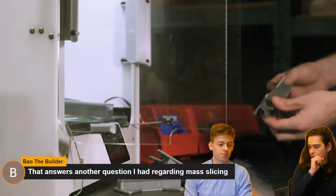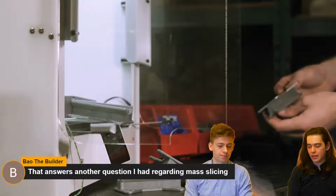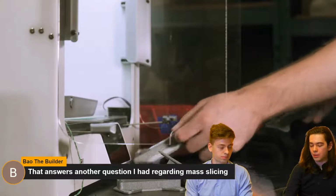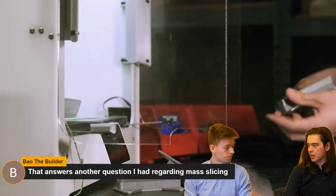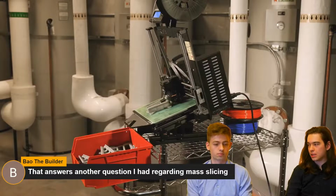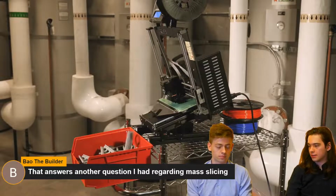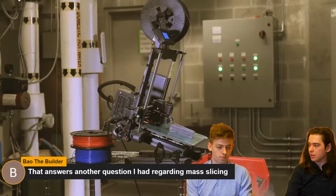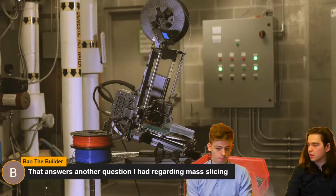Exactly. Because you would know in Pro, you would be sending it as a silk PLA job. You could have an offset for silk PLA that's plus 20 degrees. And then anytime you send that G-code as a silk PLA print, it's done.